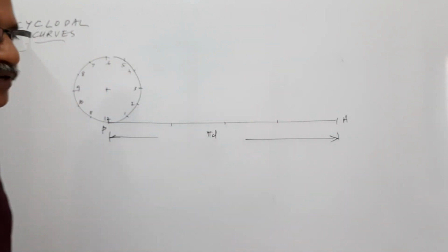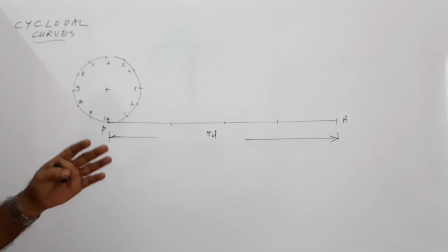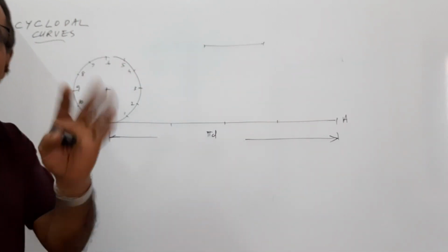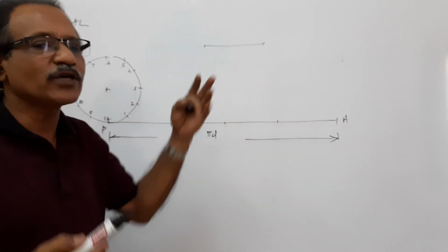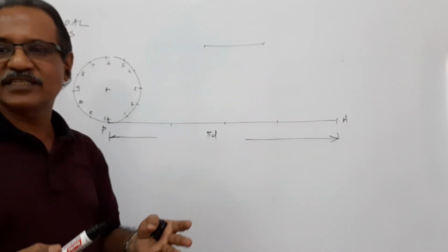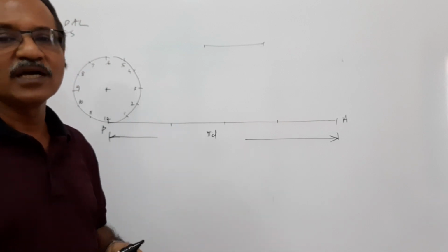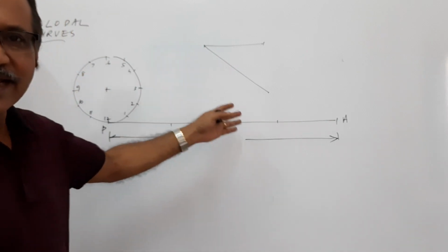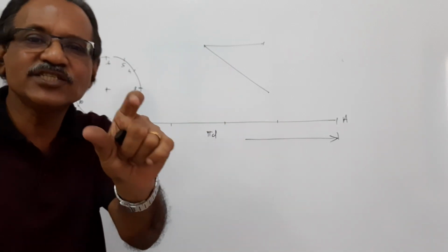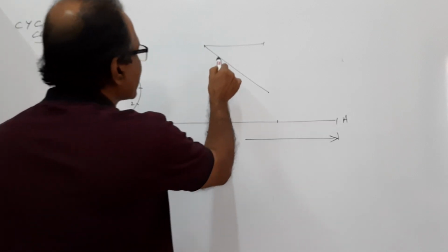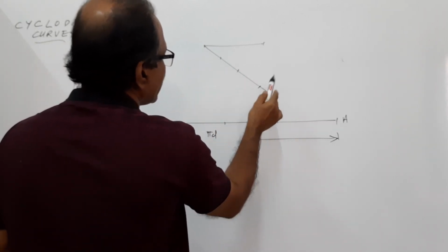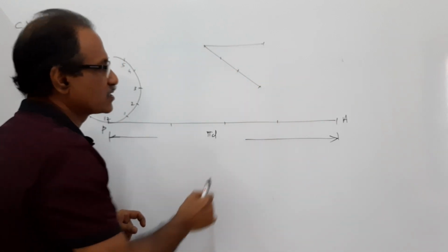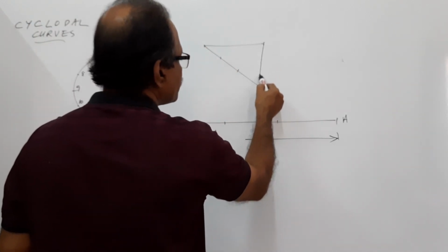You know the procedure of dividing any line into any number of equal parts. What is it? I will just explain it here. You have got this line to be divided into say 3 equal parts. If it is 3 centimeter, you can very easily divide it. If it is not easily divisible, what we do is draw any line at any angle. Take any distance in your divider or compass and mark it 3 times: 1, 2, 3. Why 3 times? Because you want to divide this line into 3 equal parts. Join the last point to this point.